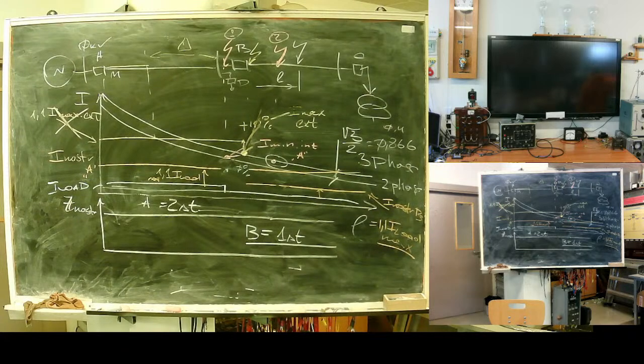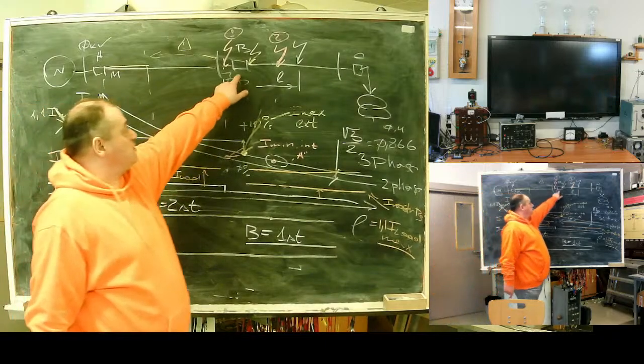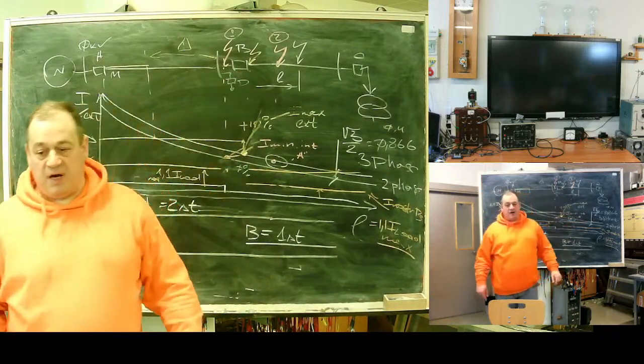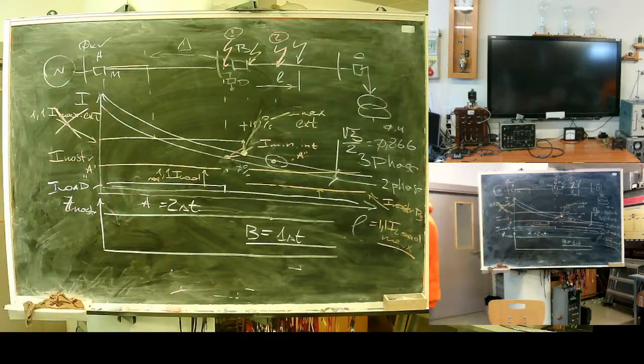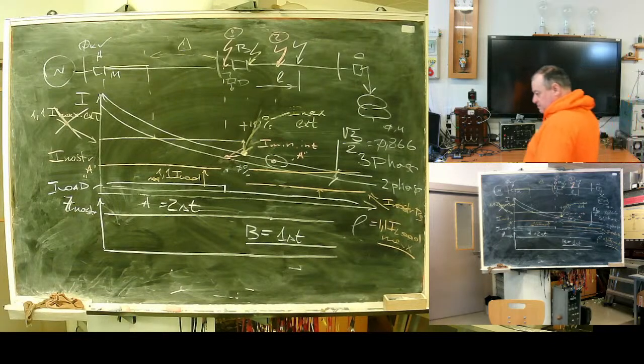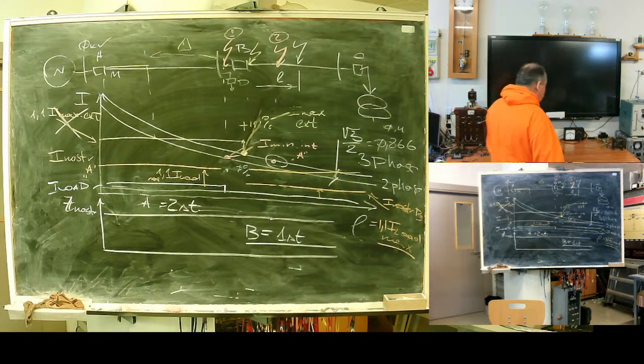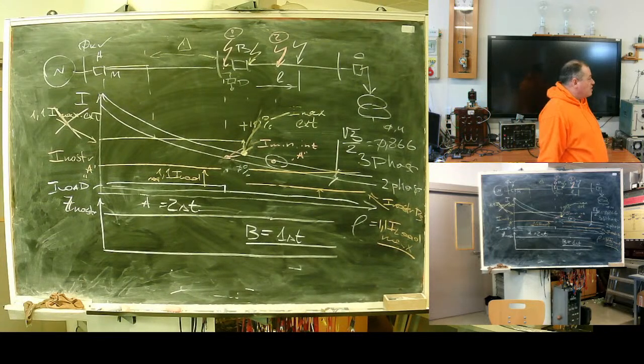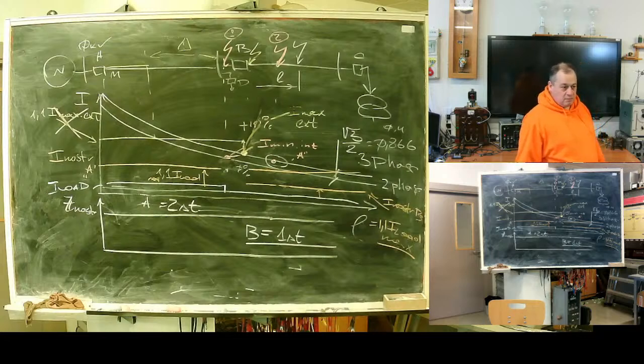A counts 2 time spaces. B arrives first. B sends a disconnect signal to its circuit breaker. What does the circuit breaker do? Of course, what is intended. Disconnects. The network clears the fault, and the current disappears. What happens with the current relays in A? No currents, no binary 1. They return.